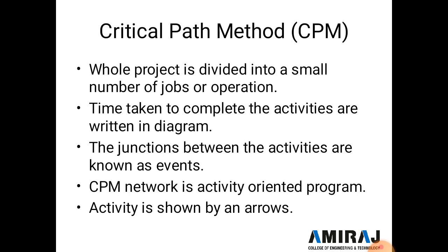So here in a CPM, the whole project is divided into a number of jobs or operations. What is the meaning of number of jobs or operations? Like if you prepare one bungalow, like a 2 BHK bungalow, the jobs are different: leveling, then excavation, then foundation PCC work, then brickwork in the foundation, soil filling work, then brickwork up to superstructure, concrete work at lintel level, then slab concrete work. So these are the different jobs or operations.